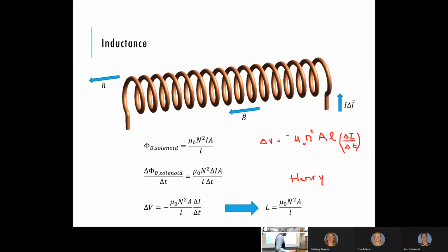So usually the physical size of the inductor gives you some idea about the inductance. Because you need more loops, which means you've got a longer inductor, or you need a larger area. Okay, well, that's going to increase the physical size. So usually you can look at it. Now, one of the other problems is that if you crack open your computer case, an inductor is also going to look cylindrical.